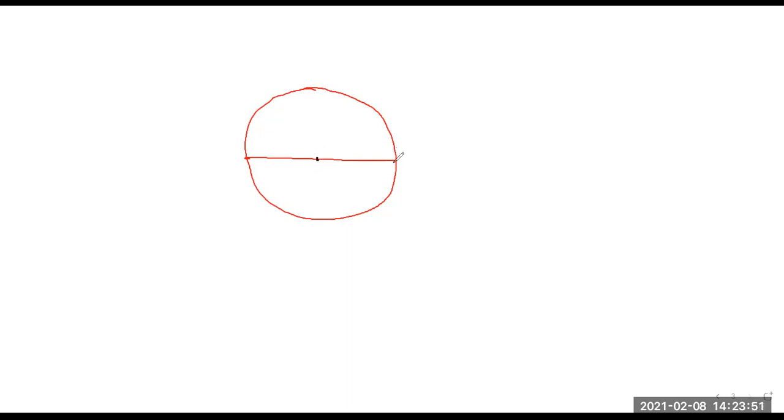So let me draw this circle, and then we will go to the actual Smith chart, because Smith chart is also right in front of you as I suggested for this lecture. You can identify that there is one resistive circle which is passing through the reading equal to 1, which is right at the center. So this particular circle is 1 plus jx circle.